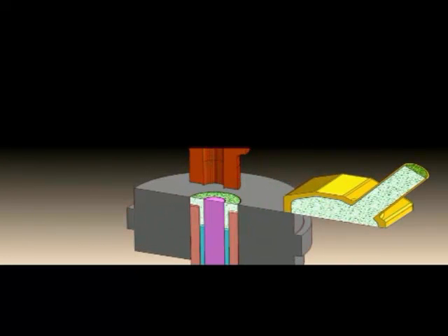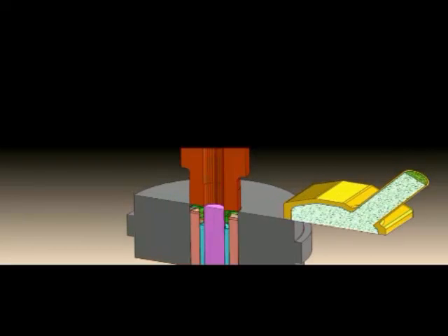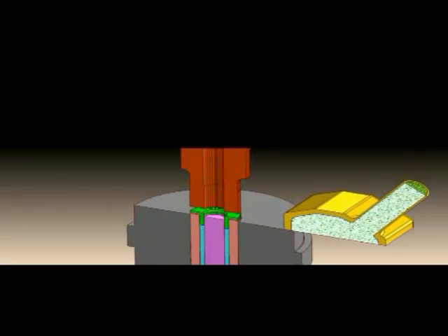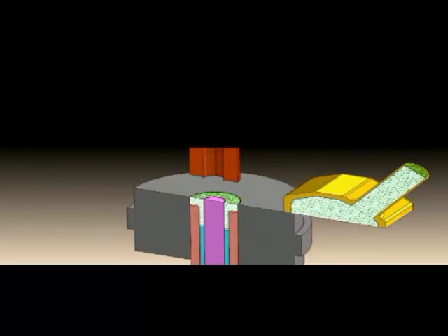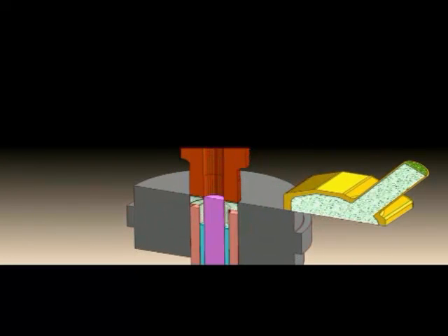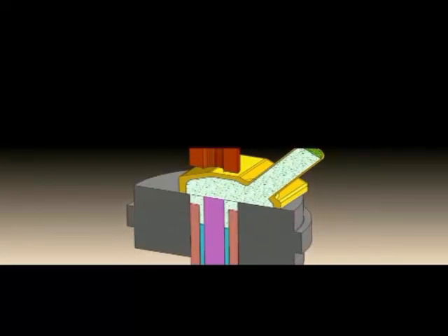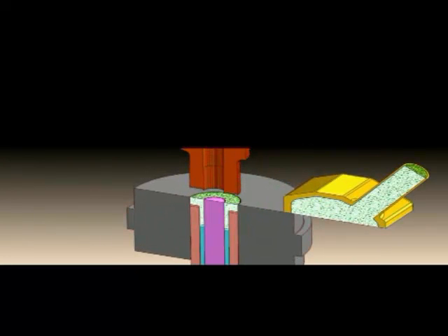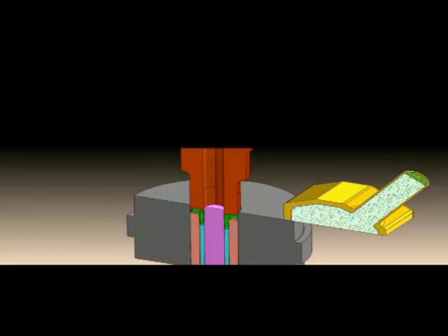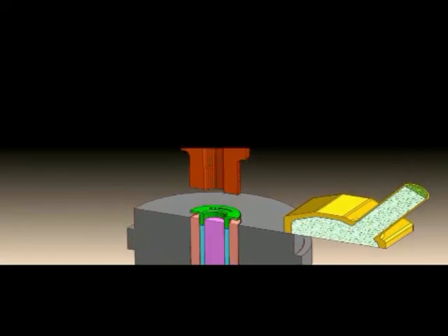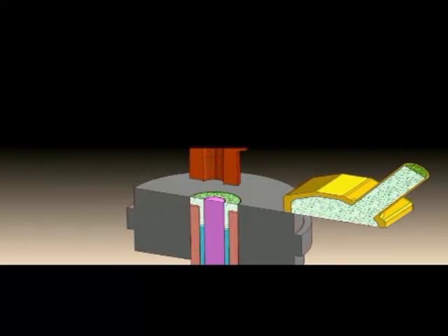One of the things that we want you to understand as we move forward, and again, caricatures are a little bit deceiving in how they present, is that the powder is held in a column. 100% of the force to create these powdered metal components is in the axial direction. So what you have is a column of powder at roughly a 2-to-1 ratio relative to your end component length. So in this case, 2 inches of powder would essentially create a 1-inch part.